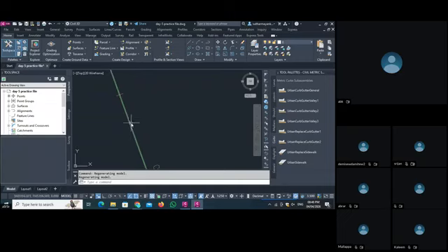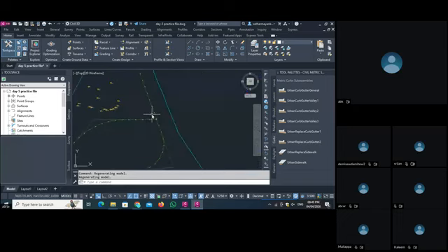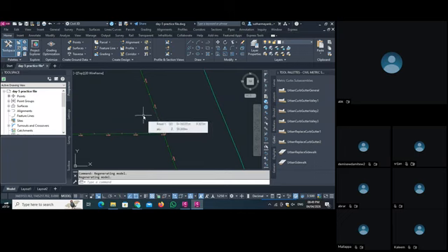Baseline is the thing where our work starts. Region is, if I select this baseline and create a full corridor here, this will be my region. And the target is, if I want to set this corridor at some distance, I have to set the target. Okay, this is the thing. I will cover it, but understand all these terms.